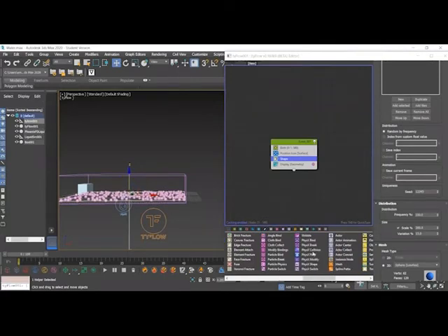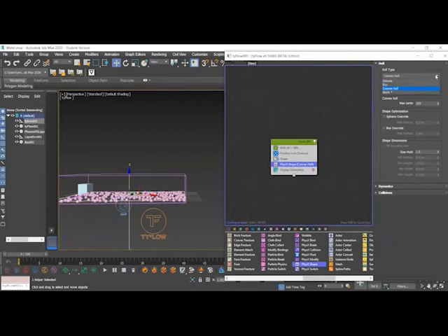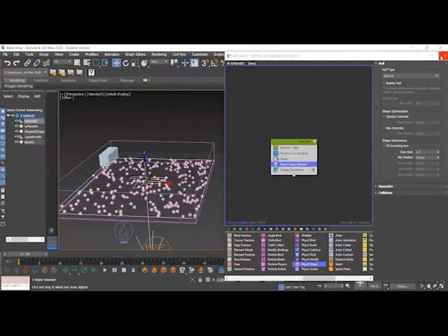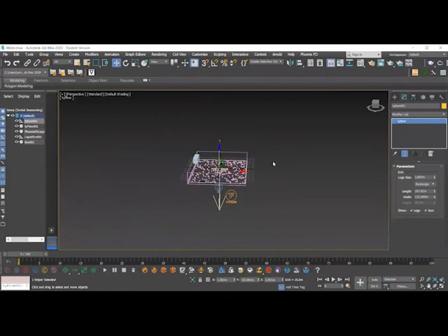We also need to make them a PhysX shape. So select PhysX shape, drag it underneath shape, and set the hull type to sphere. So now you can see that they would drop to the ground from their position because of the gravity. So then we can shut the edit window.